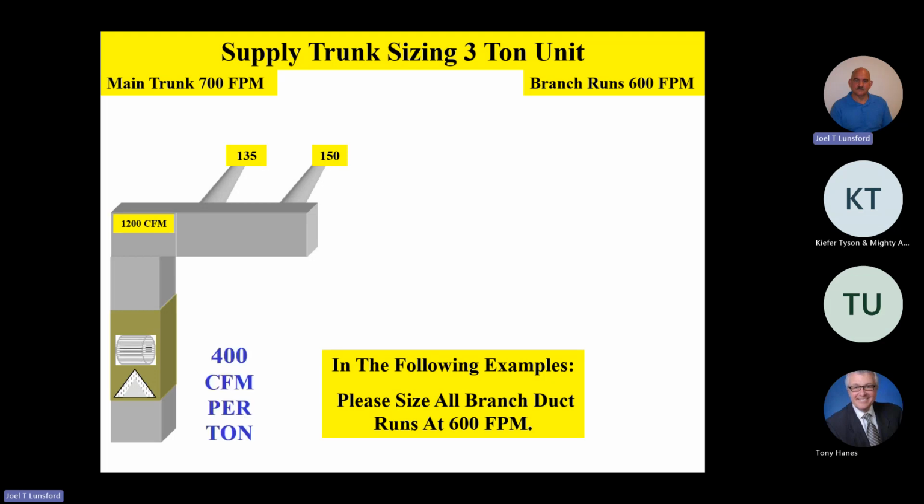600 CFM at 150 CFM at 600 feet a minute velocity. What size duct do you need for that one? Still a 7-inch, right? There you go. Okay, so another 7-inch run.